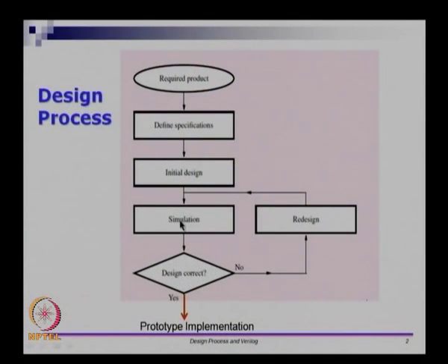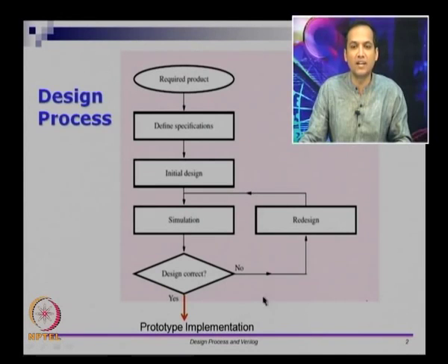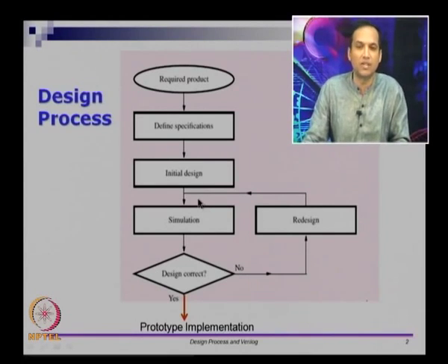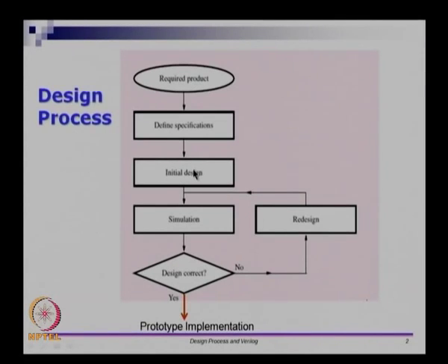Right. So this is called front end design, and this process of doing simulation, taking an initial design, writing the design in Verilog, doing simulation, finding out whether it is correct or not, and redesigning and looping through it if the design is not correct. So this process is called front end design and verification. So you do a front end design using Verilog or VHDL. VHDL is another popular language, and this process is called verification, and verification takes quite a bit of time.